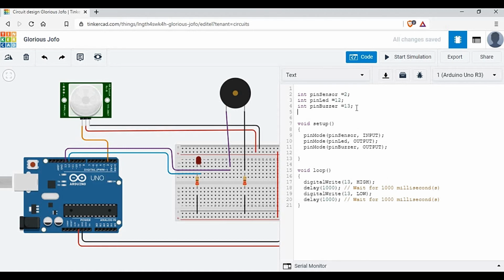And I'm going to have one more variable called PIR sensor, and I'm going to set that to 0, because I will be using this variable to detect the value from the PIR sensor. When there is a value, I want to save the signal value into this PIR sensor variable, so we can do the full configurations. I will show you how we can make use of that.